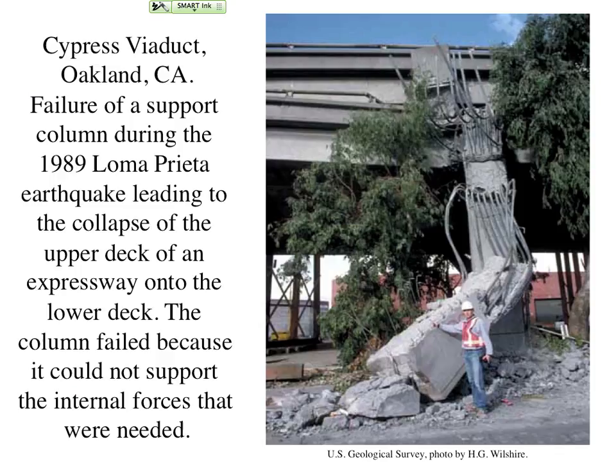This particular column failed during the 1989 Loma Prieta earthquake in the San Francisco Bay Area. It would be difficult to use our previous expression for critical buckling load to understand the basis for the failure. First, this is a composite structure. It's steel-reinforced concrete, so it isn't a homogeneous body. Second, the dynamic loading experienced during an earthquake, in particular the component responsible for side-to-side swaying, renders our static critical buckling load expression quite simplistic.